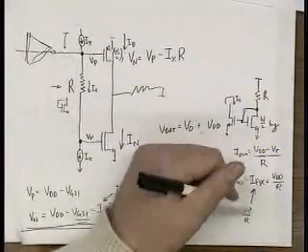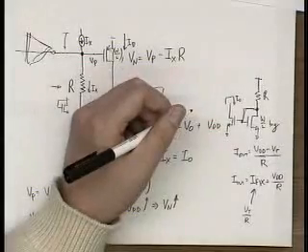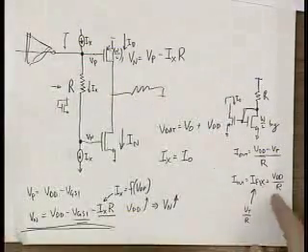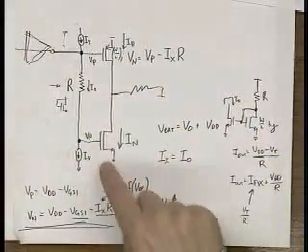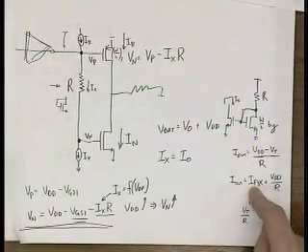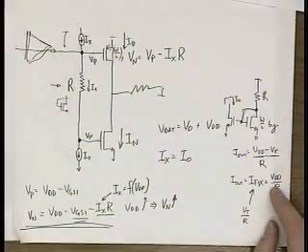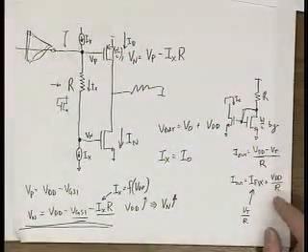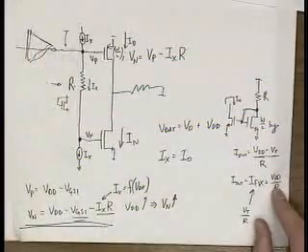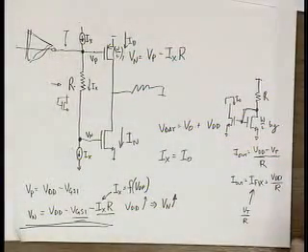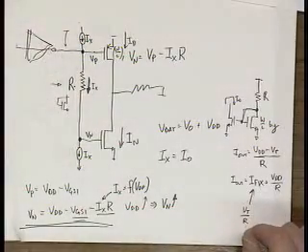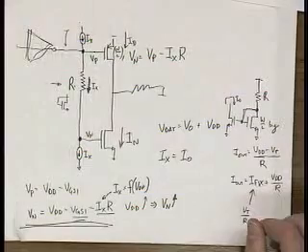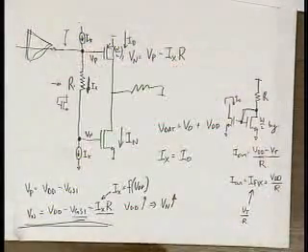So if you plug this current I out into IX, you'll get some fixed current plus some current that's directly proportional to VDD. If you size this R and this R exactly the same, or do some ratiometric design, you can get IX to be directly proportional to VDD, and hence this battery voltage to be directly proportional to VDD.